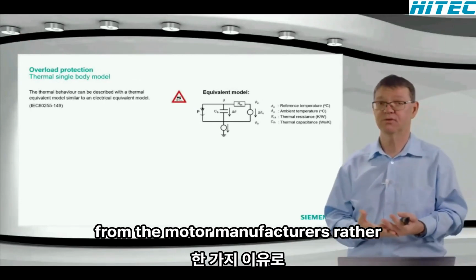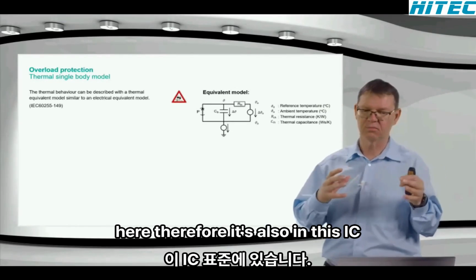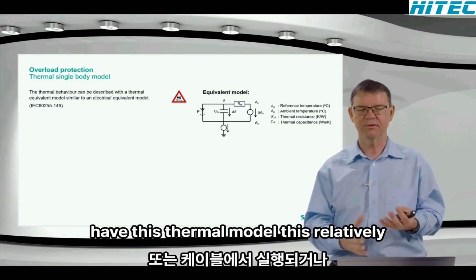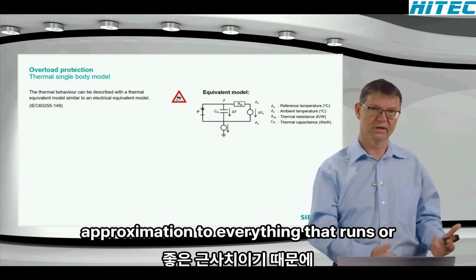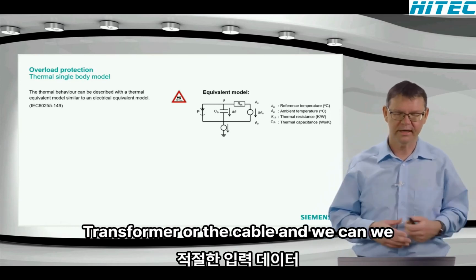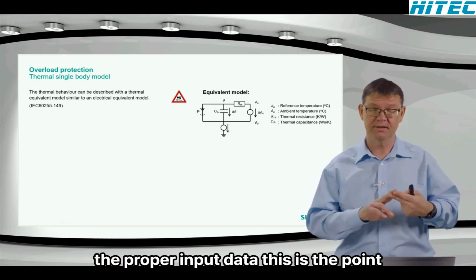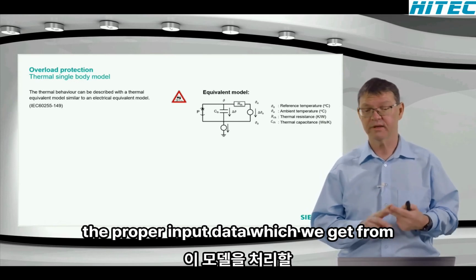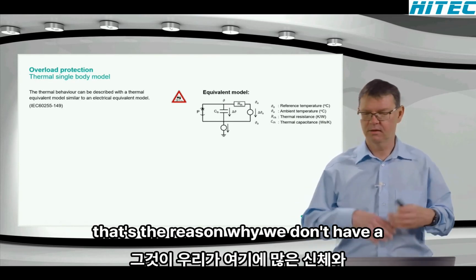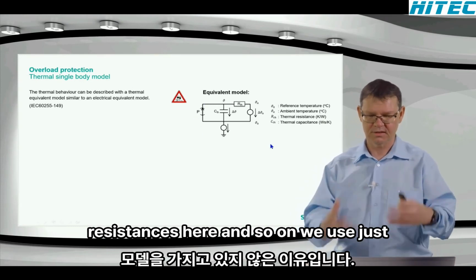The data we get from the motor manufacturer is rather limited. So we try to find a model, or we found a model here. Therefore, it's also in this IEC standard here. It's common practice. So we have this relatively simple thermal model, because it's a good approximation to everything that takes place in the motor or the transformer or the cable. And we have the proper input data. This is the point, the proper input data which we get from the motor manufacturer so that we can deal with this model. That's the reason why we don't have a model with a lot of bodies and a lot of resistances here and so on. We use just this here.